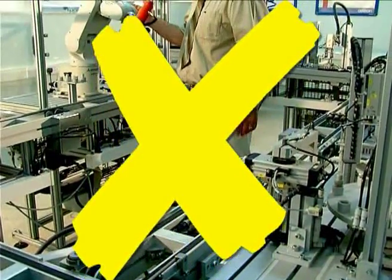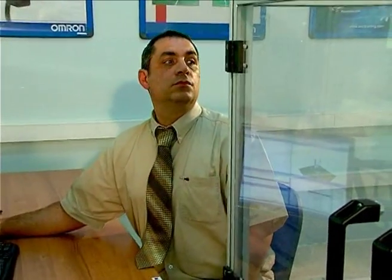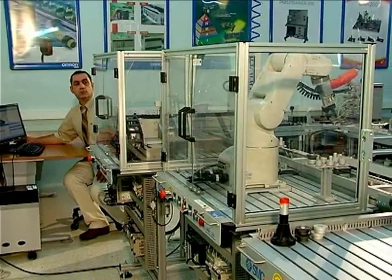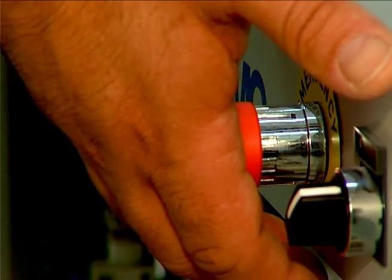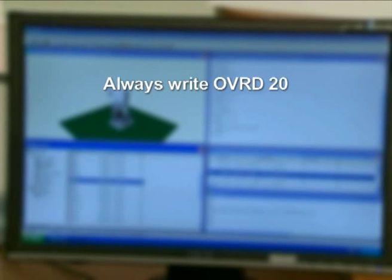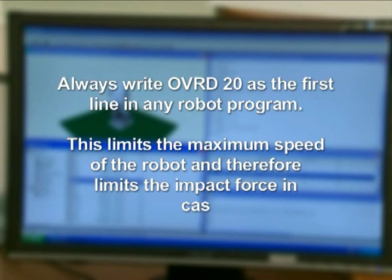Always make sure there is no one in the work cell before starting a program. Always give an audible warning before running the program. Always keep one hand at the emergency stop and observe the robot during its full operational cycle. Always write OVRD20 as the first line in any robot program. This limits the maximum speed of the robot and therefore limits the impact force in case of collision.